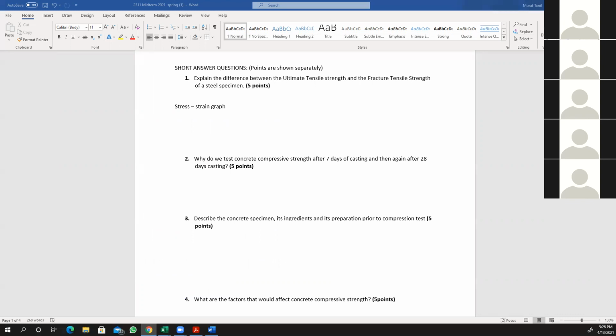If you don't have the opportunity to keep your concrete poured on the job site at lab conditions, which I have never seen, because you are out there on the site, you cannot keep the temperature between 50 and 90 Fahrenheit or the relative humidity between 80 and 85%. But what you do is use concrete curing compound. That's what we use all the time when working on concrete pavements or sidewalks. Right now I work with the Sewerage and Water Board doing pavement and drainage work. As soon as we pour the concrete, curing compound is applied to keep the concrete in good condition against shrinkage and deformation.